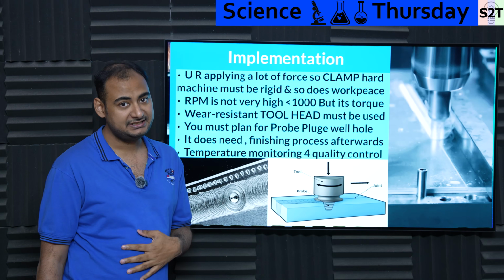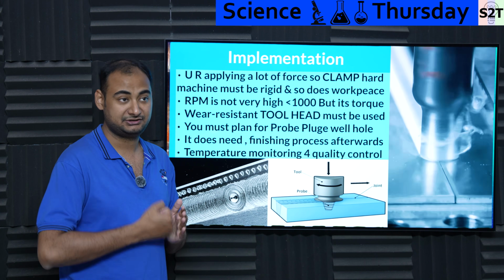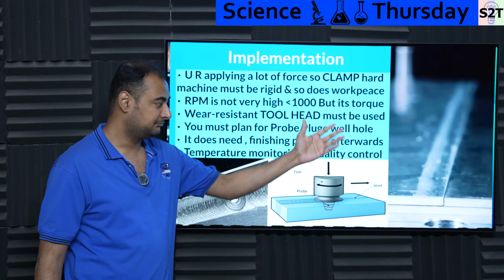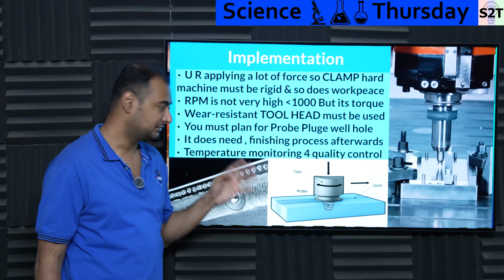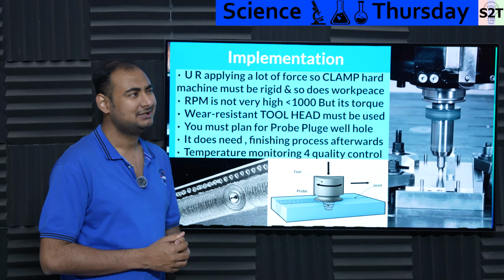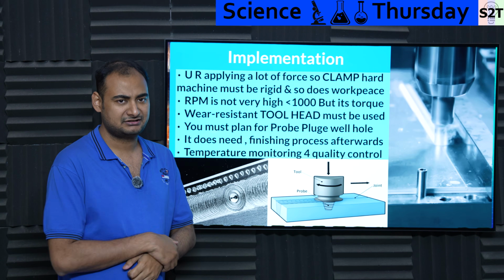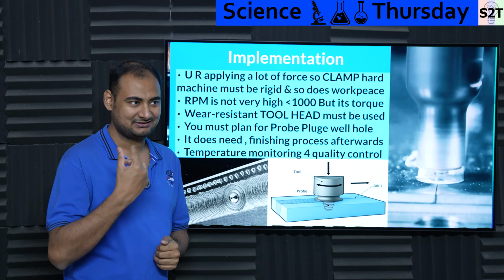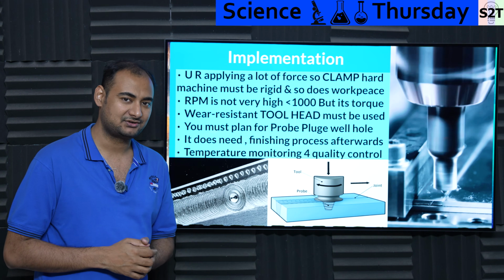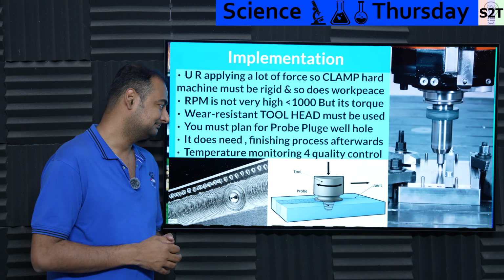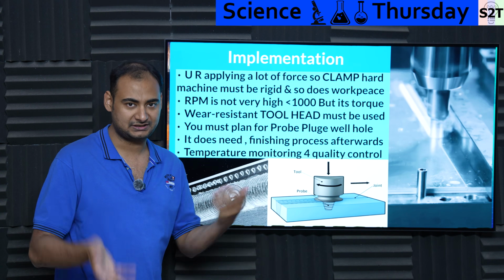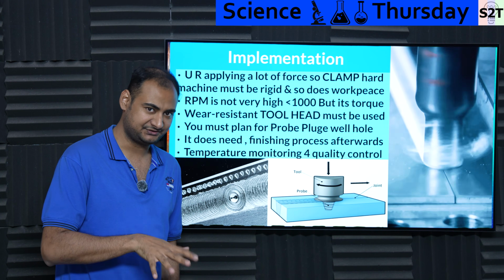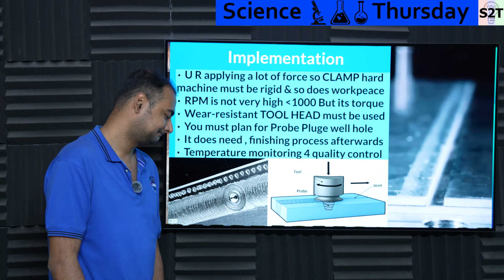And temperature monitoring is critical, because you are talking about plasticizing and you are pushing it that much. On energy level, you can go overboard and melt it. That would be a big no-no. So you do require temperature monitoring. Nowadays, it's kind of easy. You can have a certain wavelength thermal camera and just look at it. A normal wavelength will not work because aluminum is reflective, but certain wavelengths allow you to observe it. Or you could even use old school probes. So it does require a certain level of keeping an eye on the thing, so you do not go overboard.